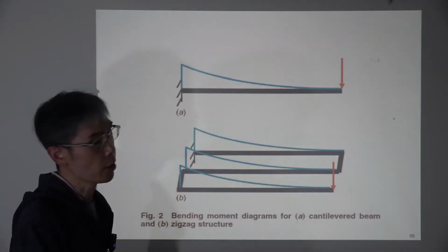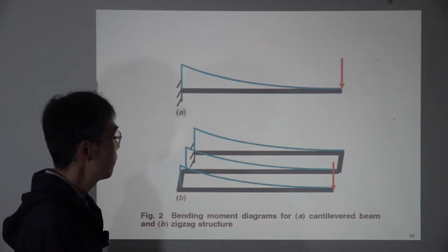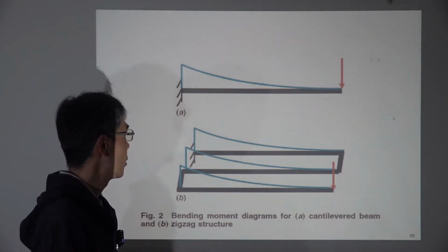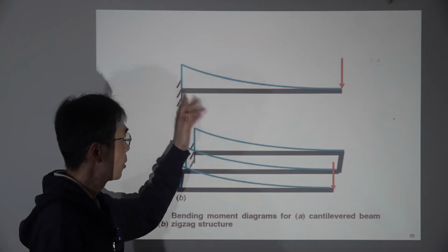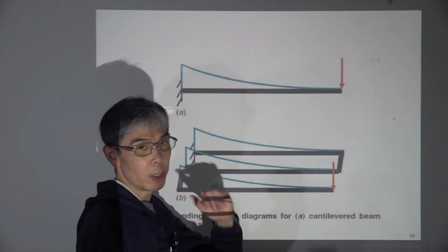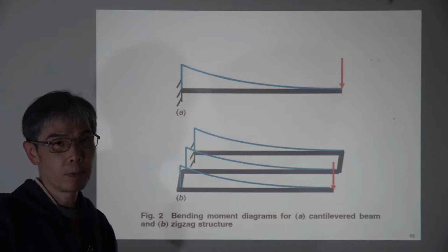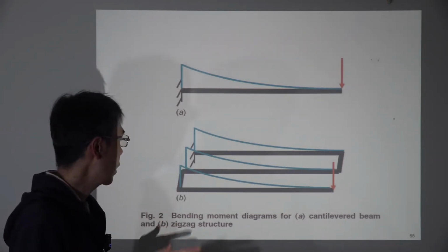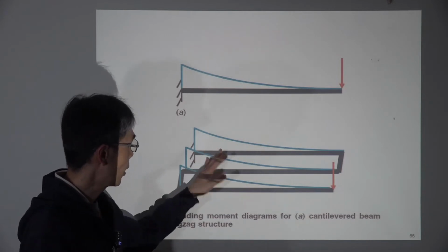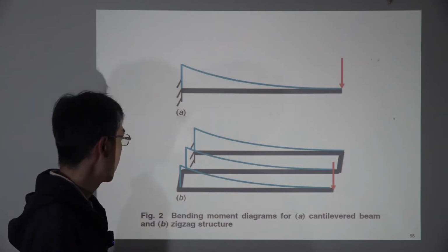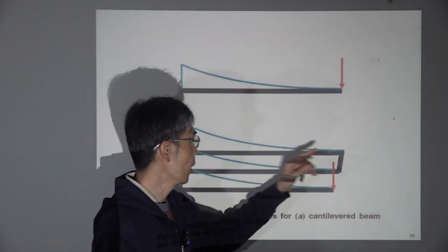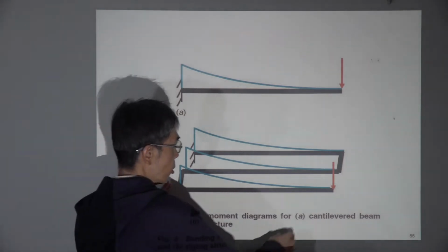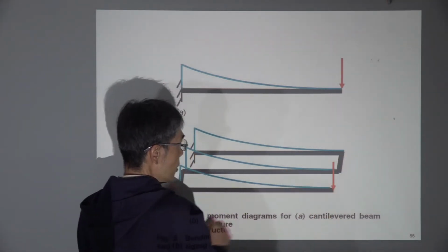And this schematic explains what's going on for a single beam structure. The vibration is in the z direction. Then the beam just bends. Bending dominates the mechanical behavior of the device. But what if we have 3 segments? In the first segment, we have not only bending but also twisting, because there's a torque applied to this beam segment.